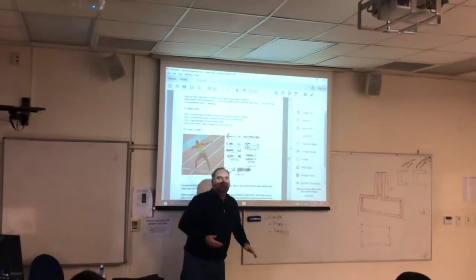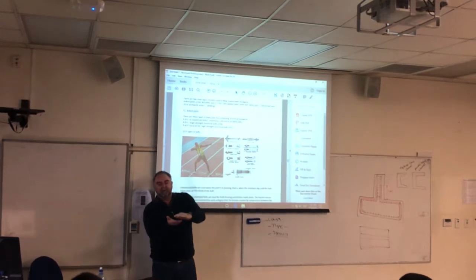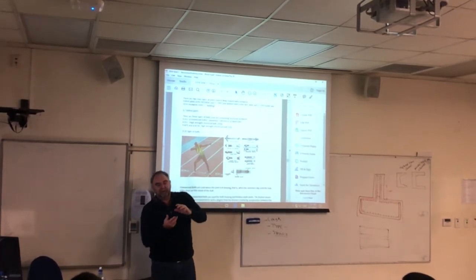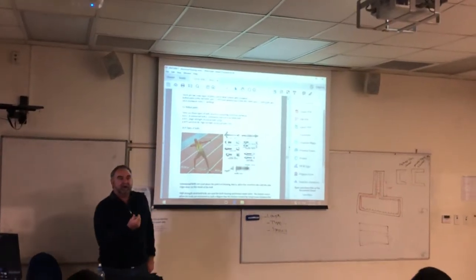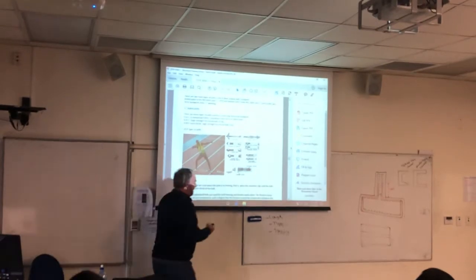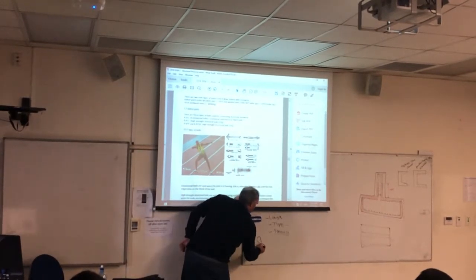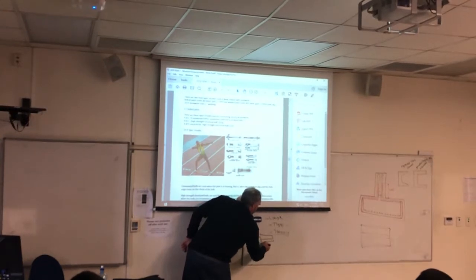The length depends on what it's going through. Is it going through a piece this big or a piece this big? We generally have enough thread on the other end of our length to tighten it up. So the length is taken from this point here to the end of the thread.